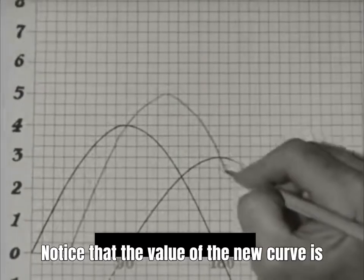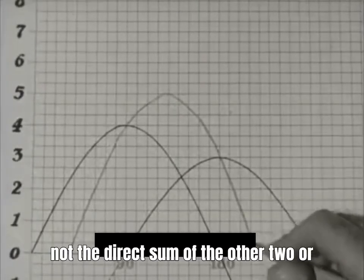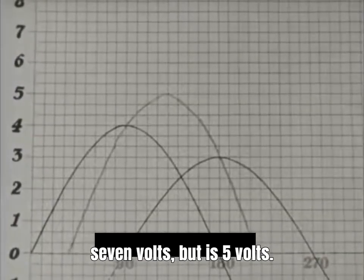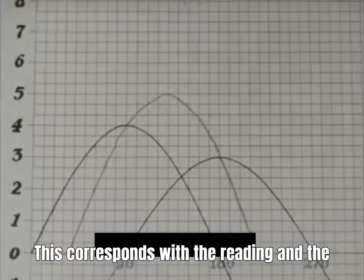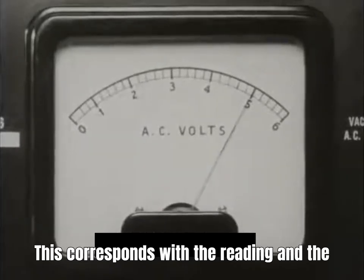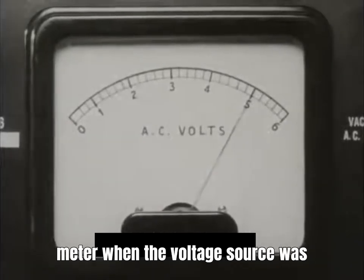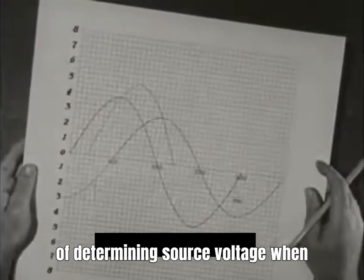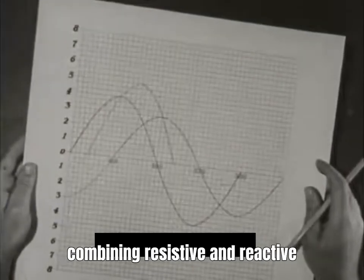Notice that the value of the new curve is not the direct sum of the other two, or 7 volts, but is 5 volts. This corresponds with the reading on the meter when the voltage source was measured. This graphic method is one way of determining source voltage when combining resistive and reactive voltages.